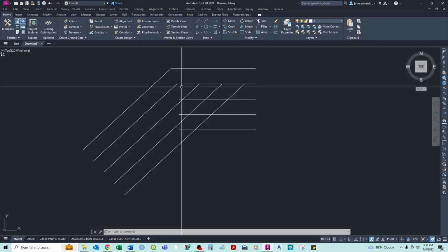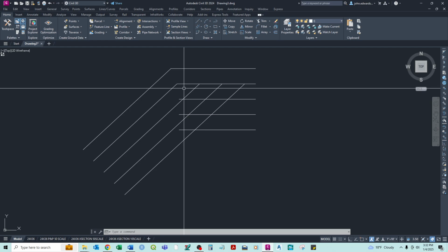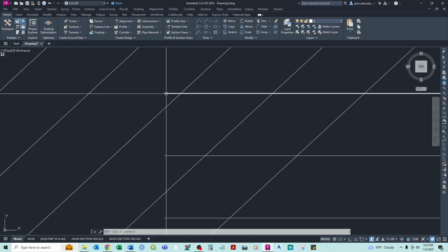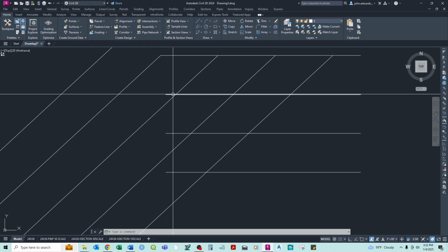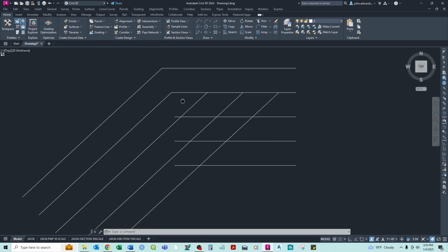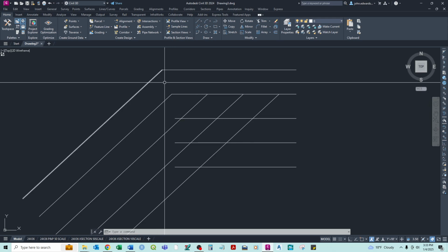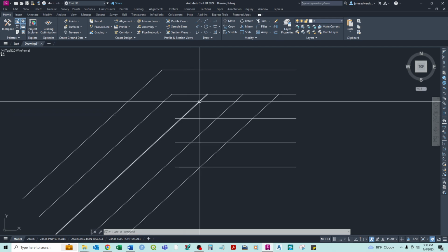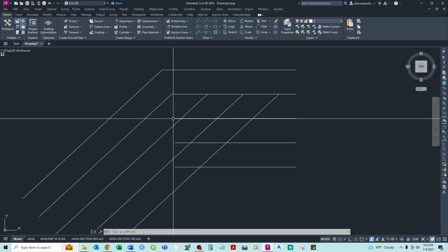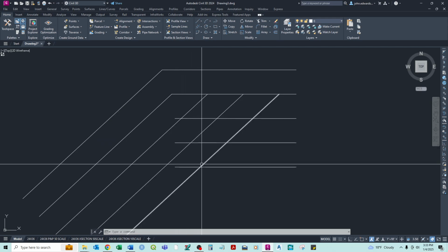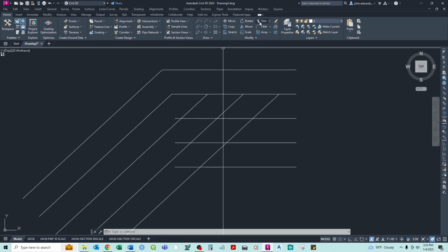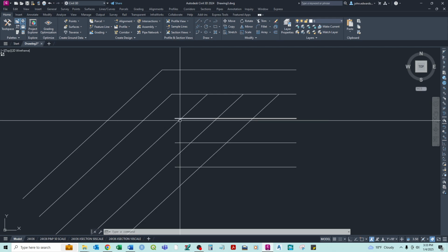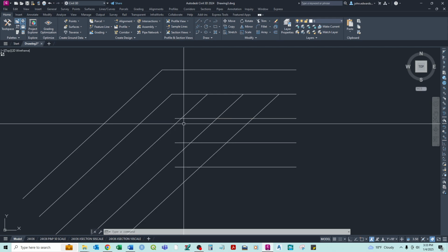So essentially the opposite type command to extend is trimming. So if you see these little places where the line sticks out between these two, say I wanted to keep this same format where they're clipped right nice together at an angle, it's already sticking too far out this way and too far out that way. What I can do is essentially use the trim command, and they have scissors, which is appropriate, to basically cut the ends off and make it perfect with that corner.